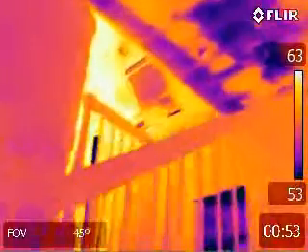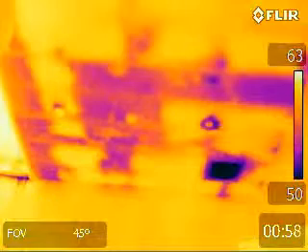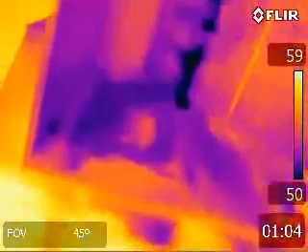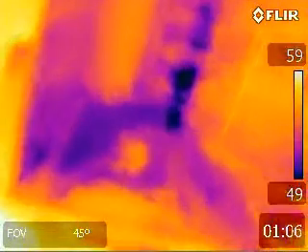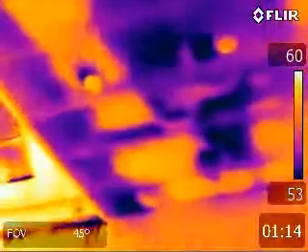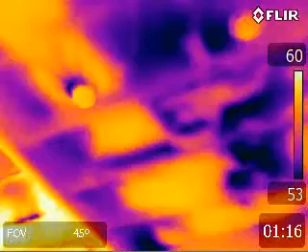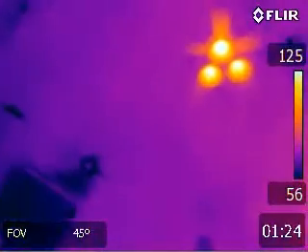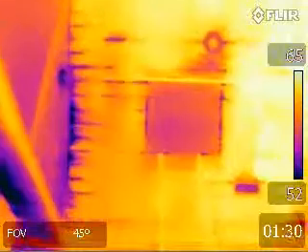This particular house has an acceptable amount of air infiltration according to the indoor air quality standard. Unfortunately, the lack of insulation is allowing heat loss into the attic area, which creates warmer conditions in the attic and is causing excessive amounts of snow meltage, which results in ice damming and extreme amount of icicles.